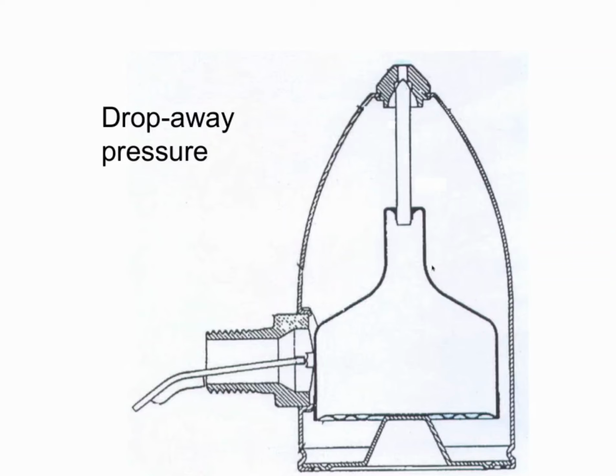And just based off of where you would find, or the application you would find this particular air vent, this is a Hoffman, as he mentioned, a Hoffman number 40. You are most likely going to find this on self-standing cast iron radiators, or I could just say cast iron radiators or steel, not steel convectors, but a steel riser pipe.